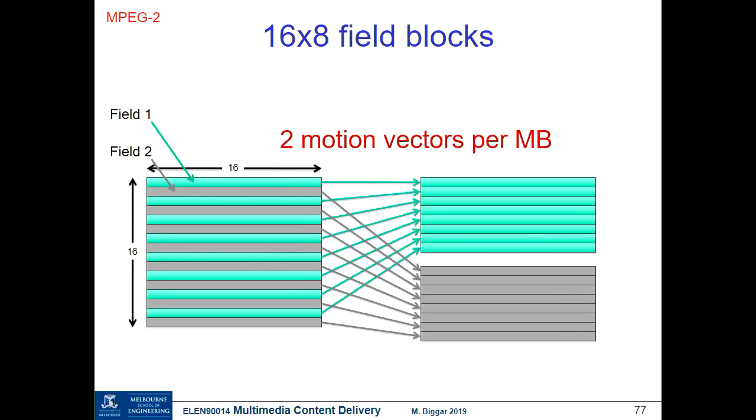Did we interlace this block again, or is it like interlaced? Sorry, well, if the signal is interlaced, then we're saying that we perform the processing, the coding, on an array of data from within the field instead of across the frame. Is that what you're asking? I mean, you took this 16 block and you interlaced it again. Oh, sorry. Yes, we encode it like this, send it to the decoder, and then the decoder puts the two fields back together.